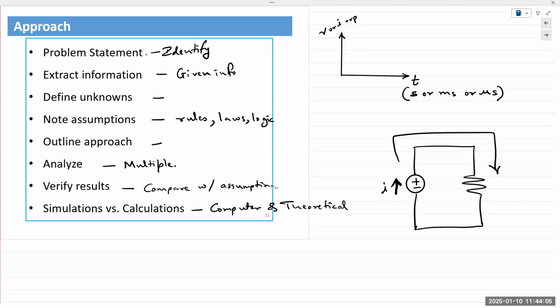Current goes through here, causes a voltage drop plus to minus. So for all other passive components, which are absorbing energy, it always goes from plus to minus. Except for a source. A source is supplying energy, so it always goes from minus to plus. Otherwise, our equations would never work. Law of conservation of energy would never be satisfied.